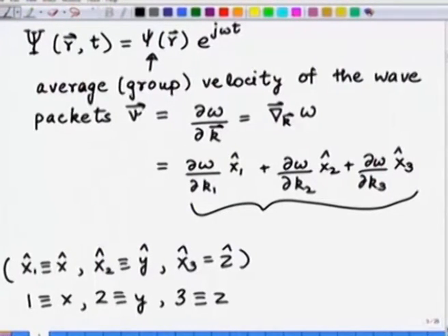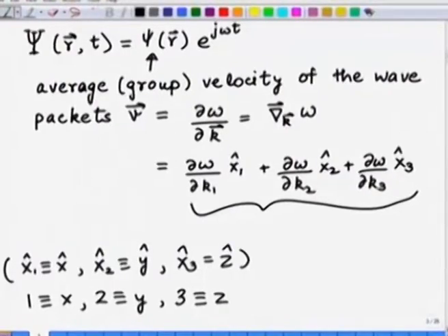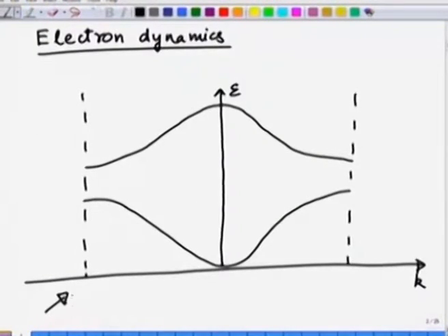That is the average velocity with which this electron wave is transferring energy. So, that is the dispersion relationship which is given here. Now, why did I do this? This is what I want to determine. I want to do it in terms of energy and k, because I want to relate it to this diagram here. I want to relate the velocity of the electron through this diagram.